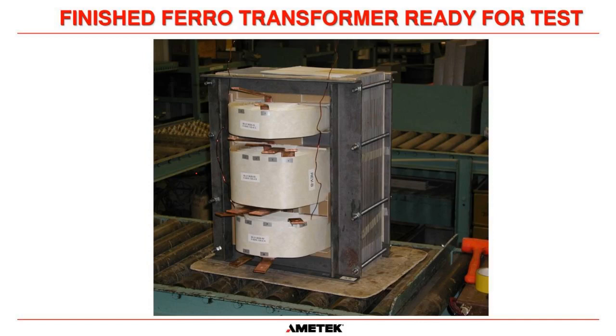Okay. You might notice in the right-hand corner, there's a dead blow mallet right there. You don't swing away like you're hitting a ball bat or something with this mallet, but what the mallet does is allow us to tap the steel together and get everything perfectly lined up. So again, we don't have any air gaps around the steel where the pieces come together. Once that's assembled, then you can see the bolts around the edge. All thread rod is used to tighten everything down.